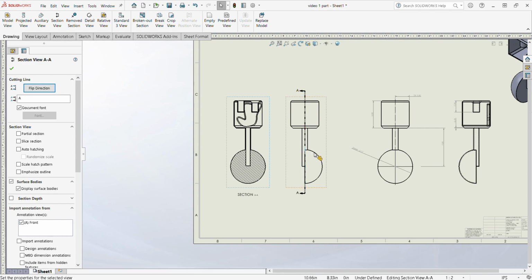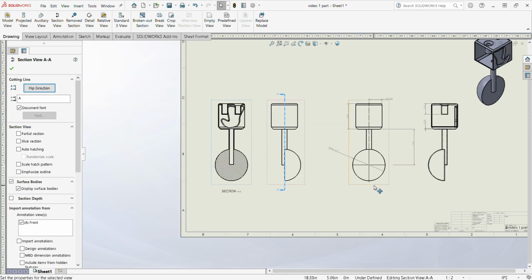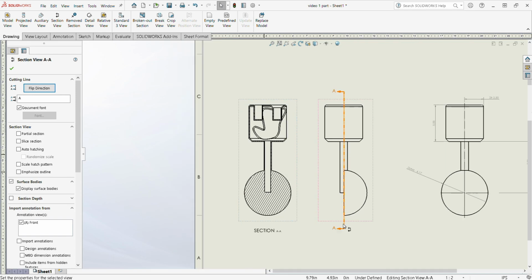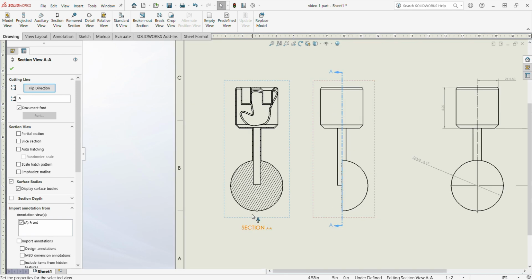So this is just taking the part and flipping it. That's the third angle projection. If you want to look into that, it makes more sense if there's people with tons of other videos. So it takes the part and flips it over, and that's how you make it make sense in your head when you're trying to understand a drawing. So that's why you can see our sorting hat and our two cutouts, because it took the section view and flipped it to the left or to the right, whichever way you want to look at that, I suppose. And then it also lists your section view and says, hey, this is the view of this. So we're looking at the view from this way, if I just drew an arrow.